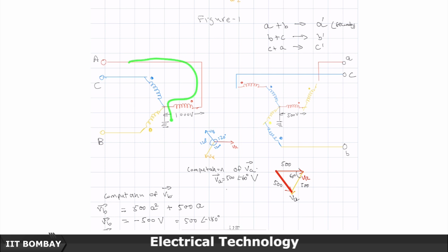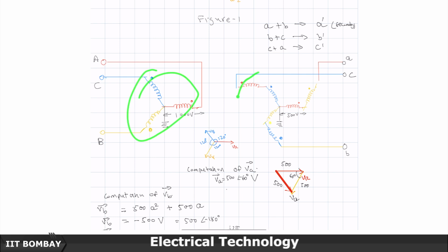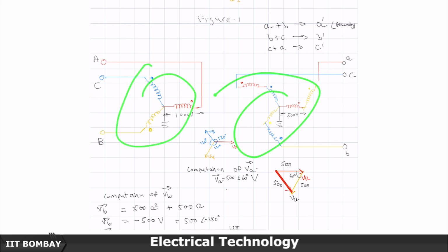So, even though I have this interconnection to ground, under such a balanced 3 phase circuit, no currents will flow to the ground, yet they are grounded. This is a speciality of this connection. We will not get into further details, but if there are triplen harmonics or there are faults and things like that, then they will have smooth passage from here. So, this transformer works like this: for balanced circuits it works as if it is open circuited to the ground, but if there is any kind of unbalance which involves ground or needs a path to the ground, it provides a path to the ground.